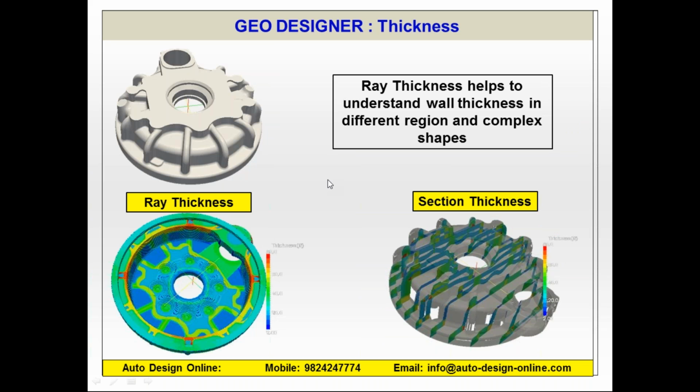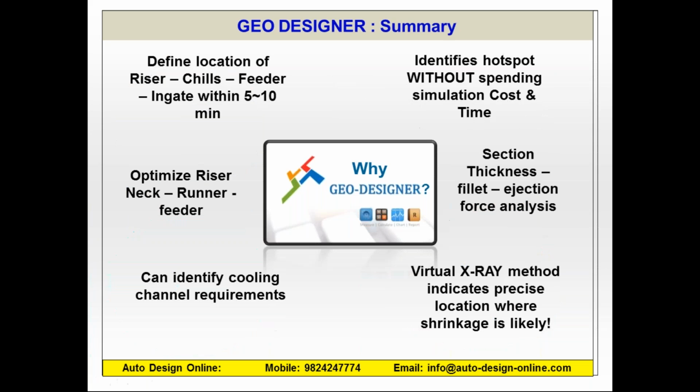Sandeep, you were referring earlier to the thickness of the cut section. So what you see here, if this is the same casting part, wherever you see the orange or red color, these are exactly the locations where you have higher thickness. And the blue color region is exactly why this software was showing this color: the blue was solidifying first, and the area in orange or red indicates which will solidify last. So this is how you can correlate this casting part and the images you were showing earlier, transparent or in color. Okay.